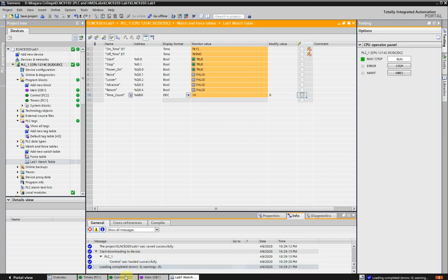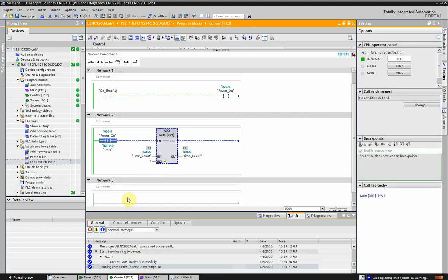I cannot see this rung turn on, it's too fast for the scan. It's actually turning on only for one scan, and I should say it's too fast for the monitor program to see this. So you can't see it working. You just know it's working because we're counting up by 1. Okay, that's one style of one-shot. Let me show you another style.